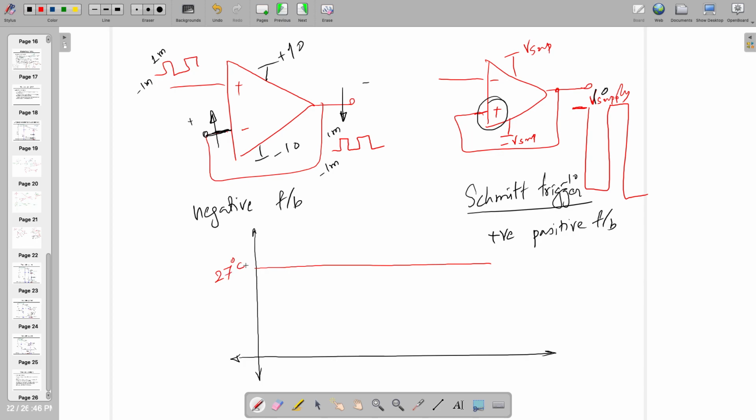It's a reference. The mechanism inside the AC tries to reach 27 degree, but when it reaches 27, maybe it will go up. In the next loop it will try to bring it down, and maybe after some time you will get exactly 27 degree. So if it is going down, then it's negative feedback, which is what was happening here.